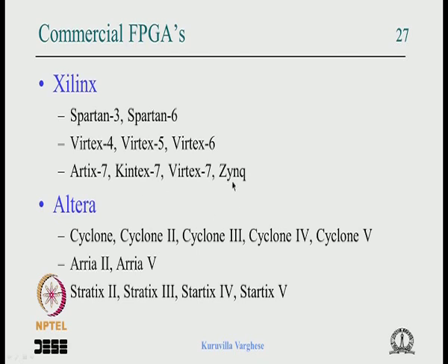Okay. Xilinx also has a new device called Zynq, which is nothing but a fabric like Virtex 7 plus dual core ARM processors built in. That is not built into the fabric of the FPGA, it is in the same silicon chip. So it's a hard ARM processor which can clock at very high speed. So a complete software hardware solution, a high performance software hardware solution, can be implemented in an FPGA.